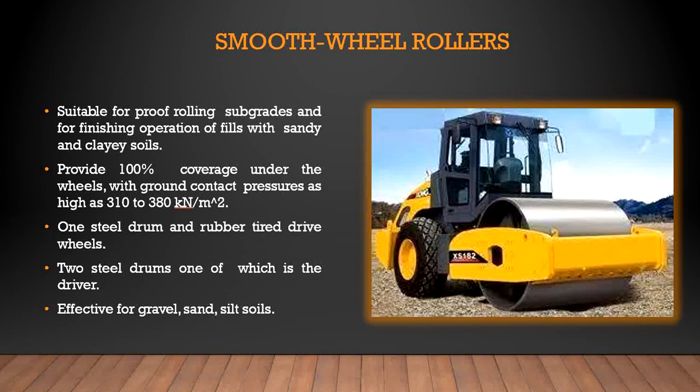The common weight is 80 kN to 100 kN, although the range may be as much as 10 kN to 200 kN. The pressure may be of the order of 300 Newton per linear centimeter of the width of rear rolls. The number of passes varies with the desired compaction. Usually 8 passes may be adequate to achieve the equivalent of a standard Proctor compaction.